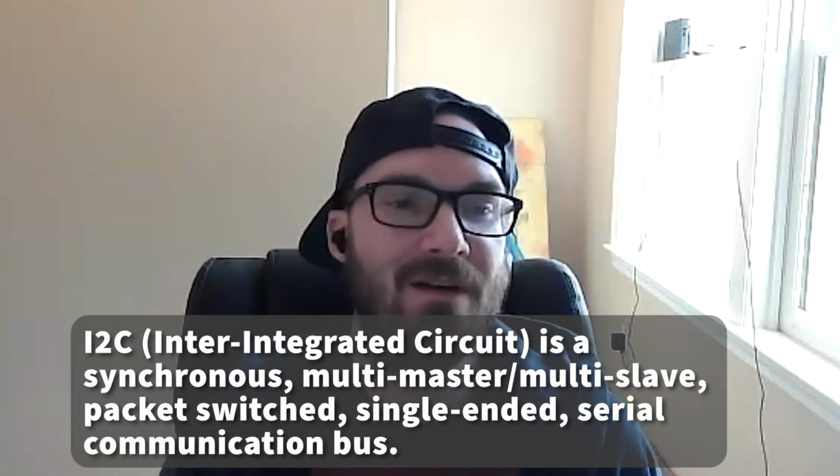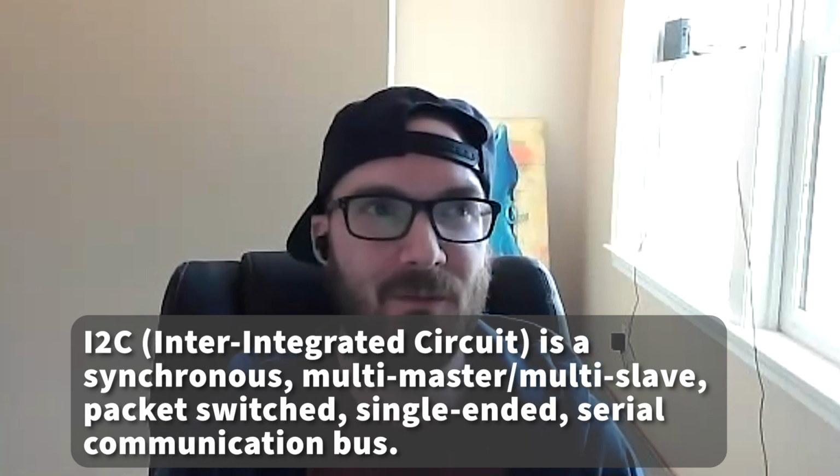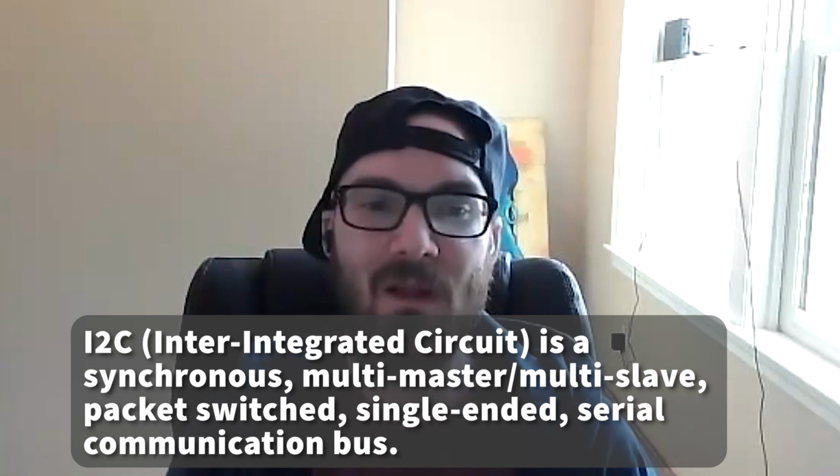Well, there is actually a second microcontroller that monitors the keyboard matrix. Its sole purpose in life is to monitor that with GPIO, and then it speaks an I2C protocol to the main processor. That main processor can be the Raspberry Pi, or it could be a microcontroller sitting on the Xiao bus, Xiao footprint, whatever we call it.